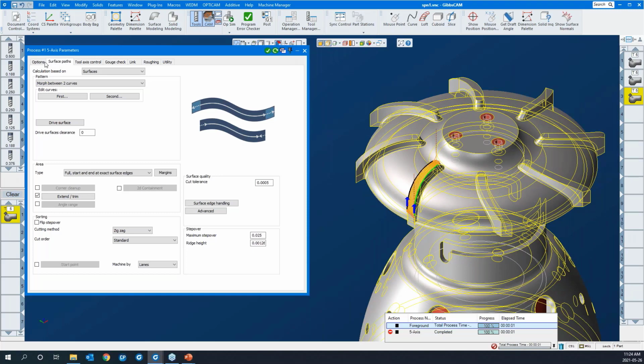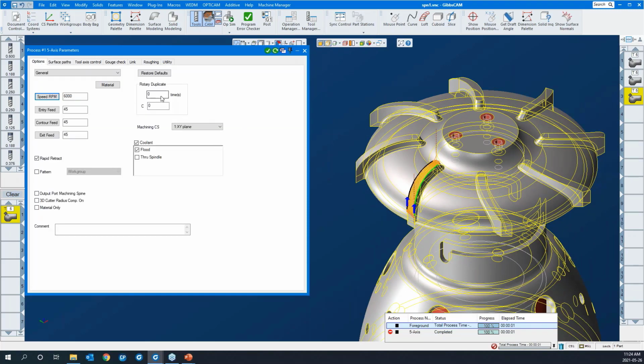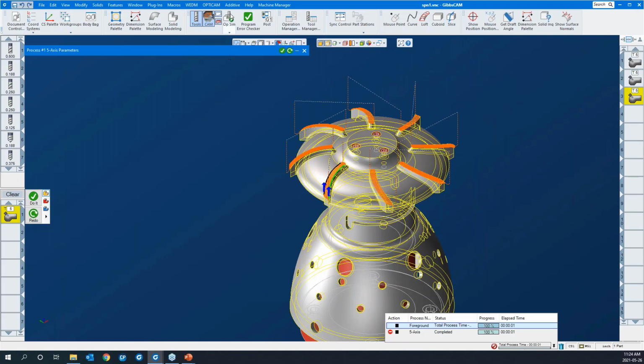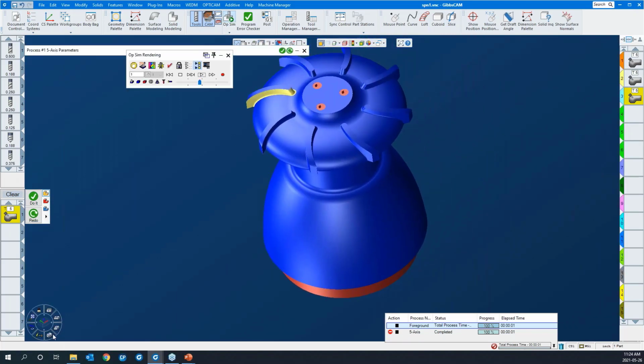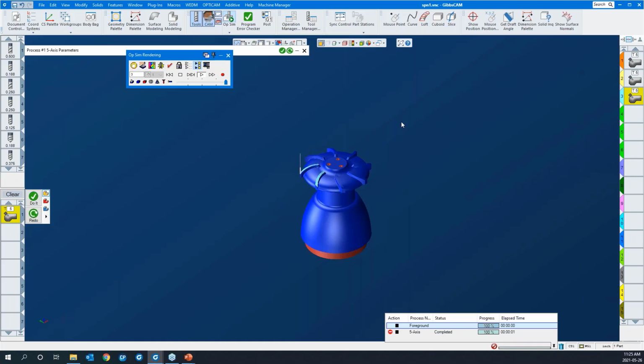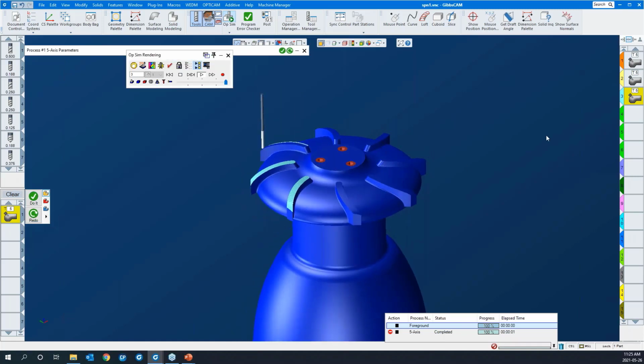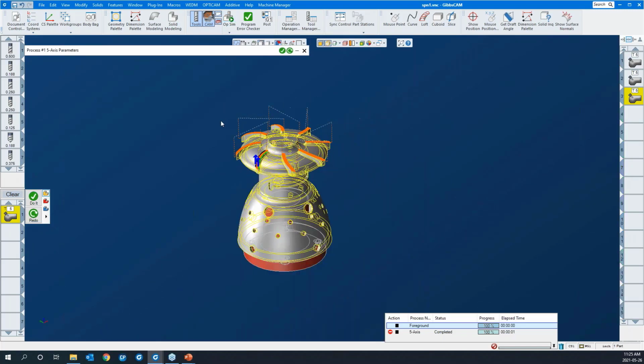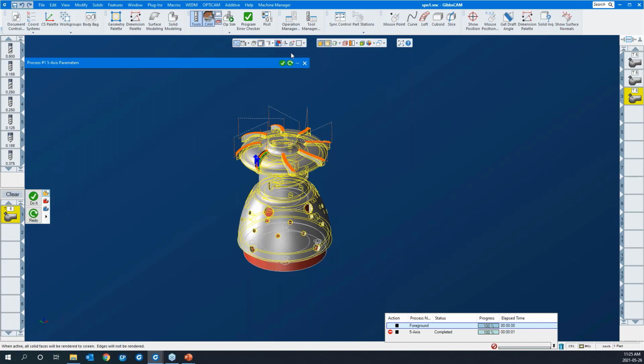One more thing we can do here is I'll go back to the options tab, and we can duplicate this toolpath 7 times over 45 degrees and say redo. Like so. I'll just run the simulation again and hit play. Away it goes. Of course, I would do that at the end to all of our operations so that the entire part was cut. I'll turn off edges here.